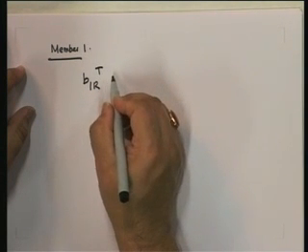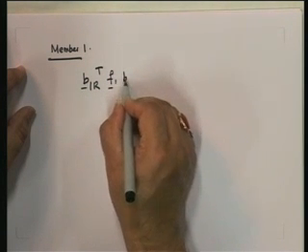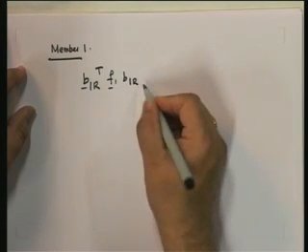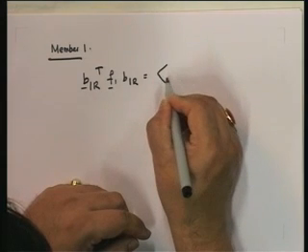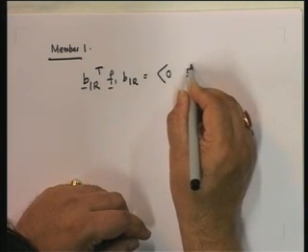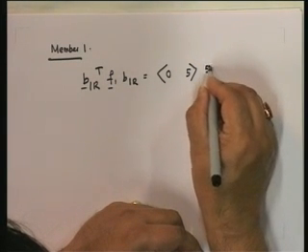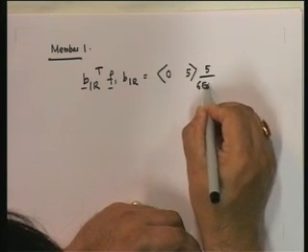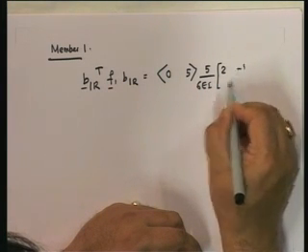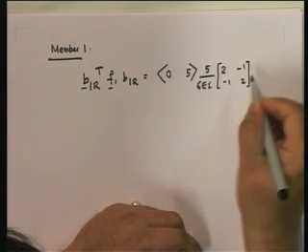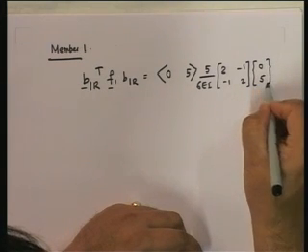B1R transpose F1 into B1R. So what is B1R? B1R transpose is going to be 0, 5. And what is F1? L upon 6EI. L is 5, so 5 upon 6EI, times the matrix 2, minus 1, minus 1, 2. And here we have 0, 5.